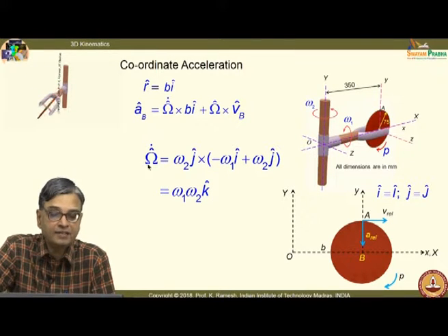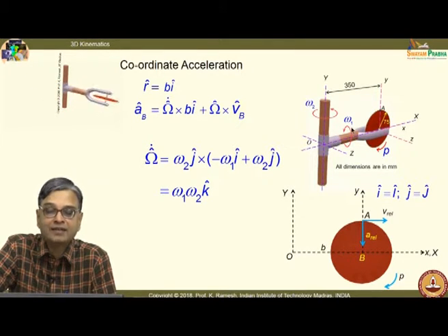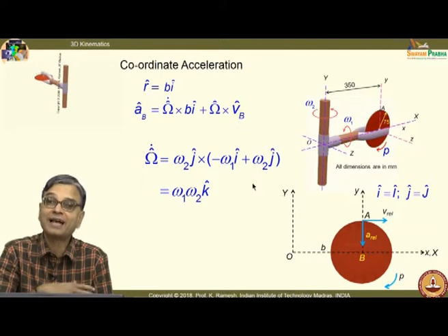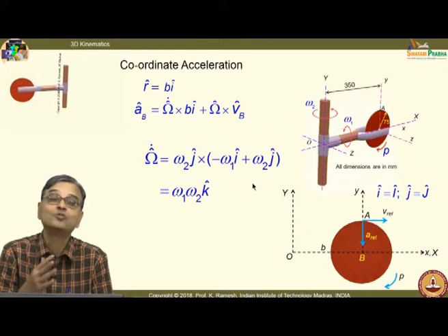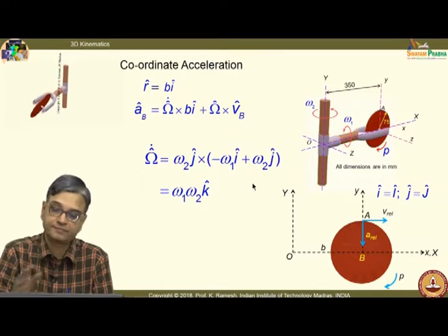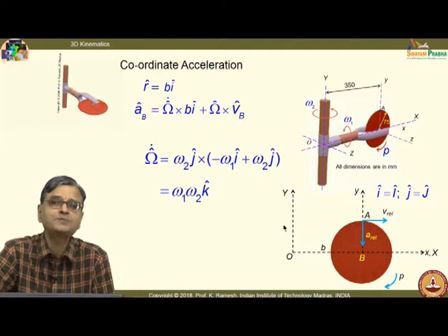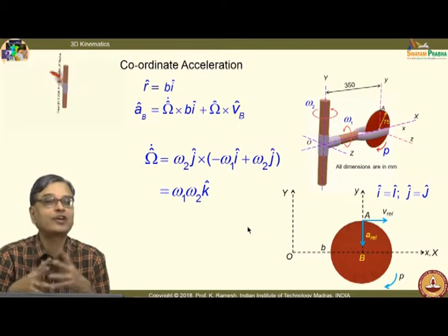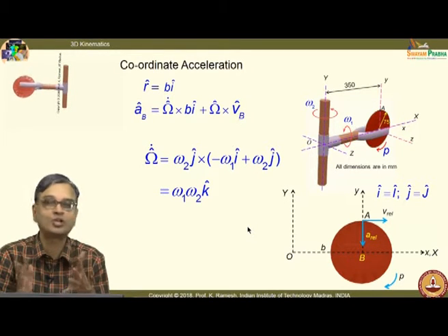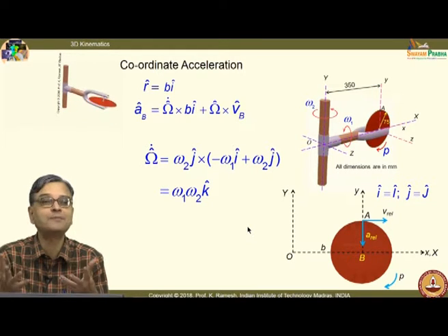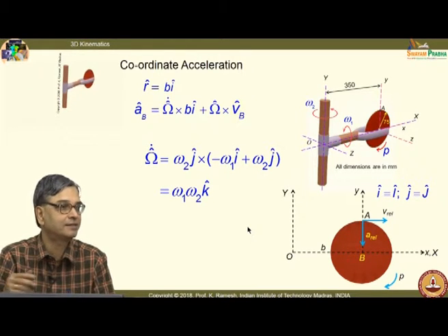So, you should recognize, even though these angular velocities are constant, because of the directional change, you still have capital omega dot, it is not 0. So, it is a very nice problem combining the fixed point rotation and rotating frame of reference. Once you have solved a problem like this, then you have many recipes for you to attack a problem.